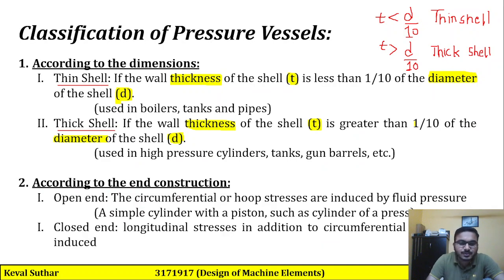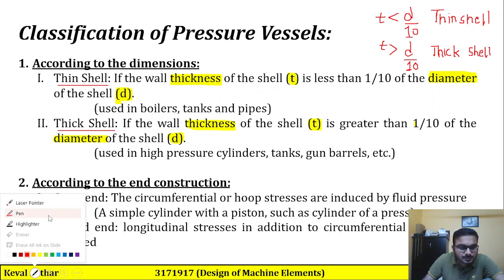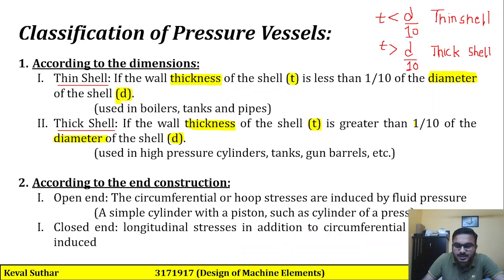And in case of closed end, the longitudinal stresses in addition to circumferential stresses are induced. So here if you see, in case of open end, circumferential or hoop stresses are induced, and in case of closed end, longitudinal stresses are induced in addition to the circumferential stresses.